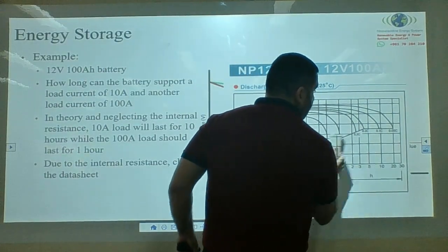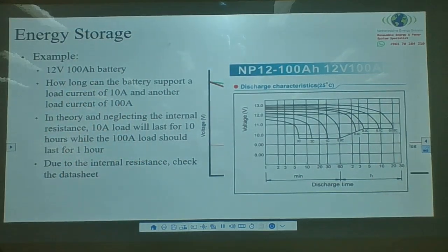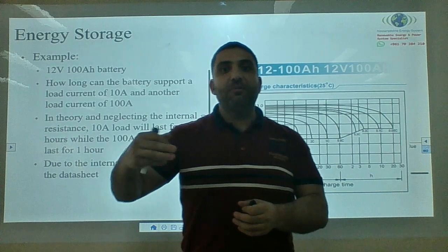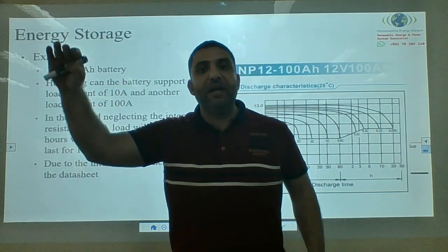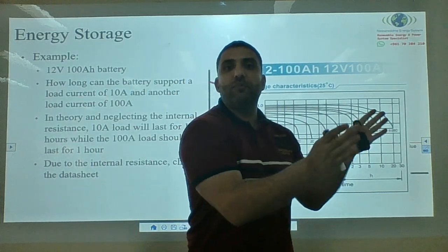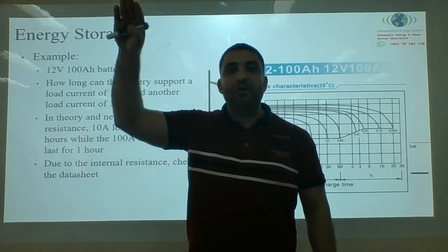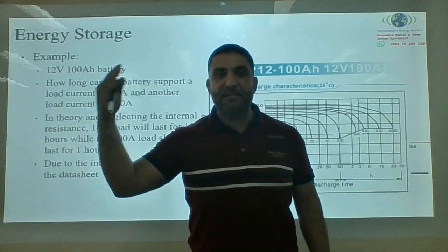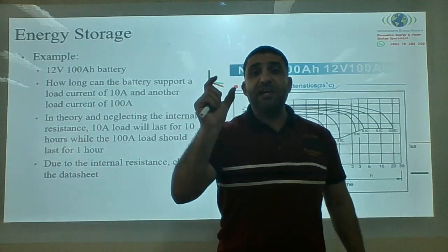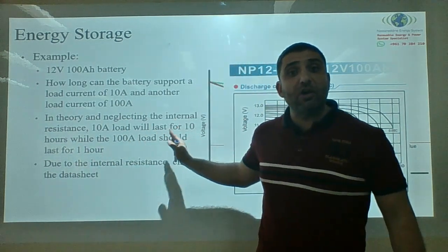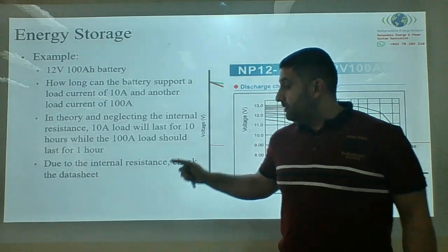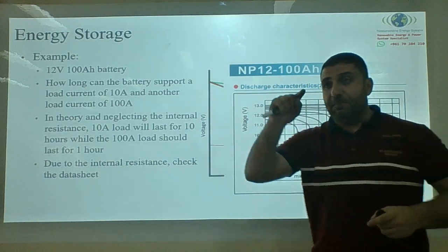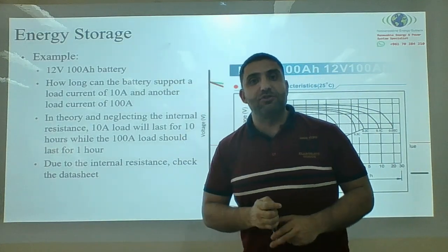So now, as a photovoltaic design engineer, you should ask your client, can you tell me what your load is? Can I see your load profile? Or you generate the load profile for your client to make sure that, for example, between 12 and 1, or between 5 p.m. and 6 p.m., I have a discharge current of 50 amps. Can my battery stand this? Maybe not. It depends on your voltage setting.